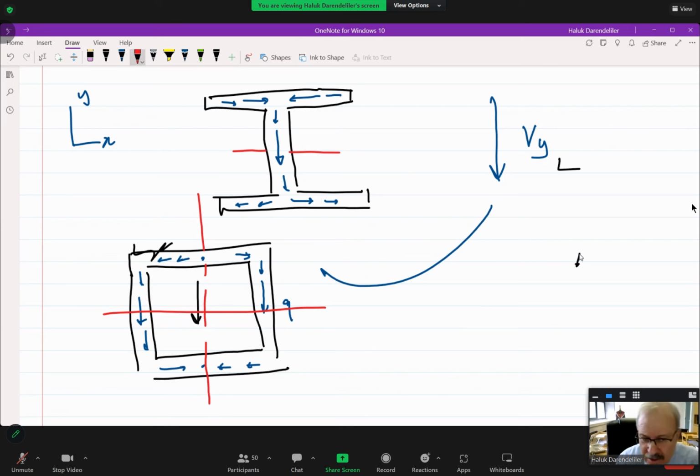The other thing is this. If we are looking for stress here, now look, on this portion, at this point, we have two stresses. One is due to this vertical section, because there is no way to transmit force from here to here. So this is the shearing stress, which is tau on the XY, with respect to ZX.